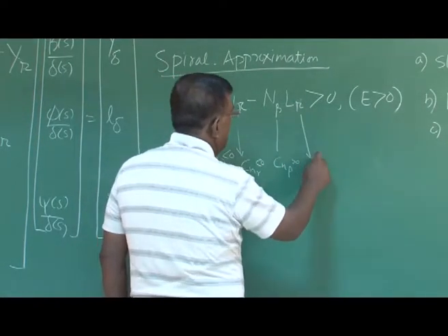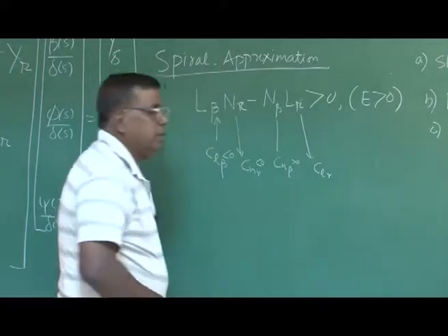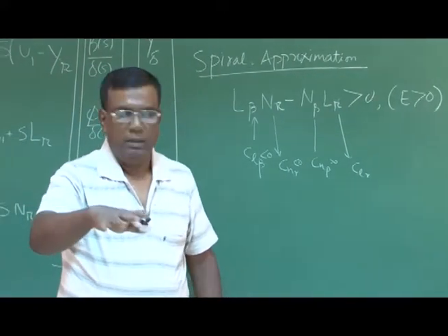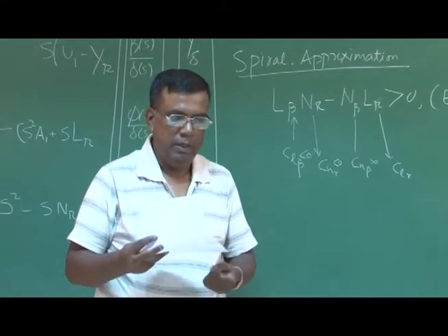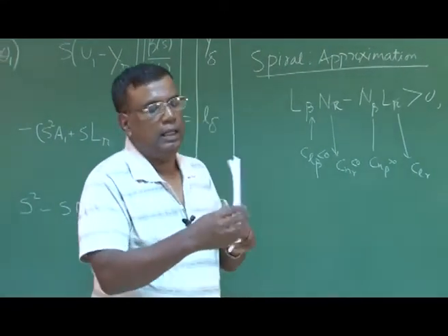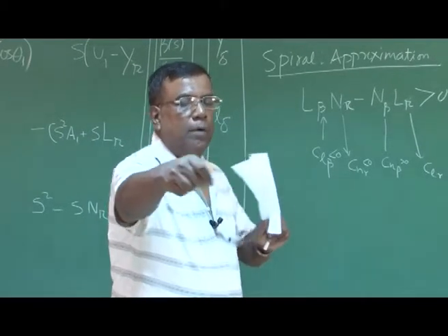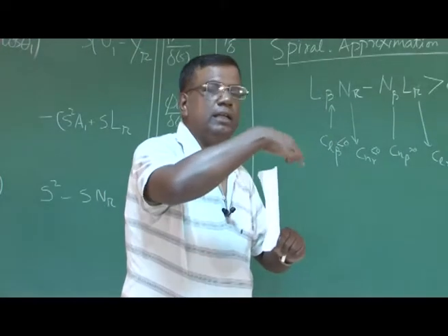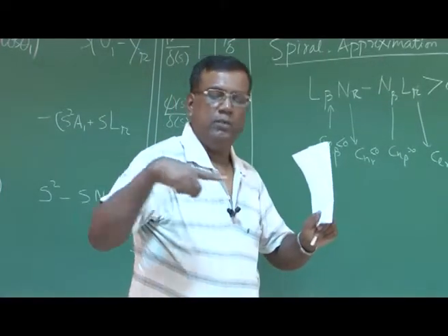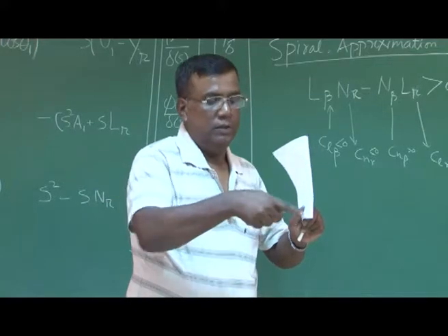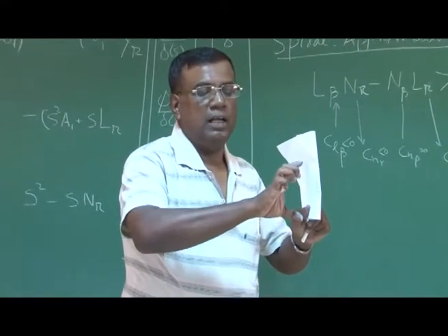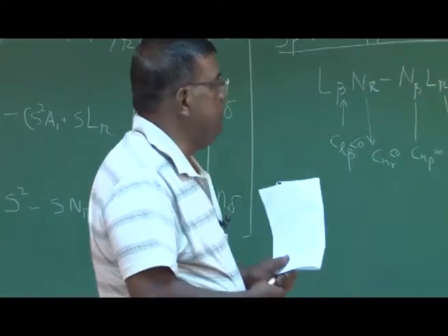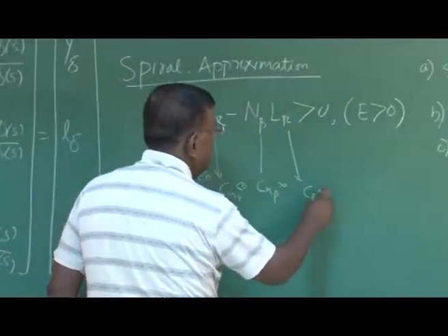And this is C L r. And C L r, you understand, if the airplane is having a positive yaw rate like this, let's say, this is the vertical tail, this is the airplane. As it goes positive like this, it is pushing the air in this direction. So it will experience the force in this direction, and this force into the distance from the fuselage center line will give me a rolling moment. So the vertical tail contribution to C L r is also positive.